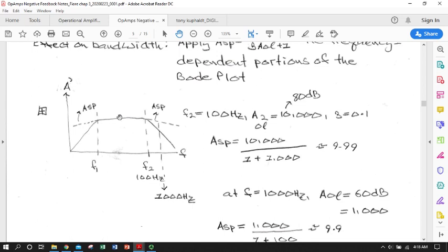This is where we want to work. Gain is frequency independent. Since all op amp circuits have a certain amount of lagging capacitance or capacitance on the output, we encounter that same kind of 20 decibel, in this case loss, with an increase of frequency in our lagging region here at the high frequency.